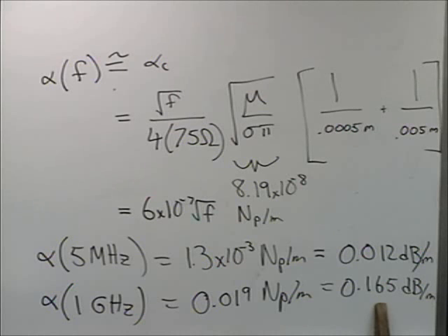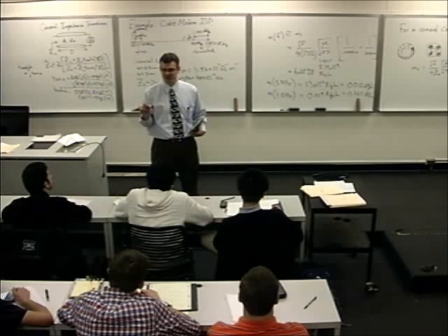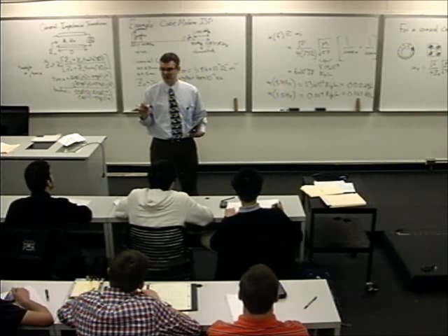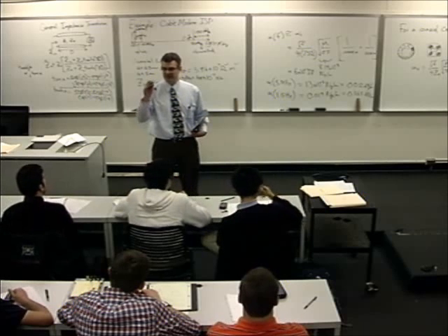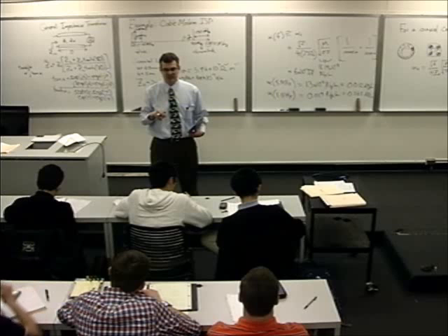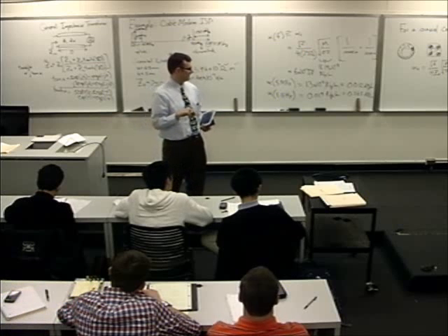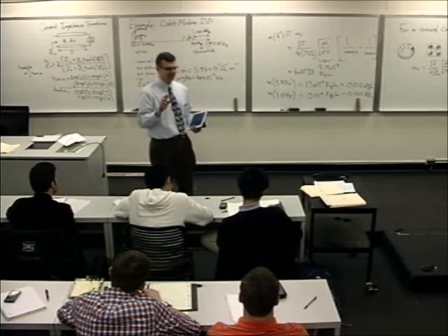What is that in the linear scale? Yeah, that's a factor of 40. I now have 1/40th of the power that I originally started with. And so this is why you want to let the infrastructure amplifiers transmit the lossy frequencies, and keep the set-top boxes transmitting the weak stuff.